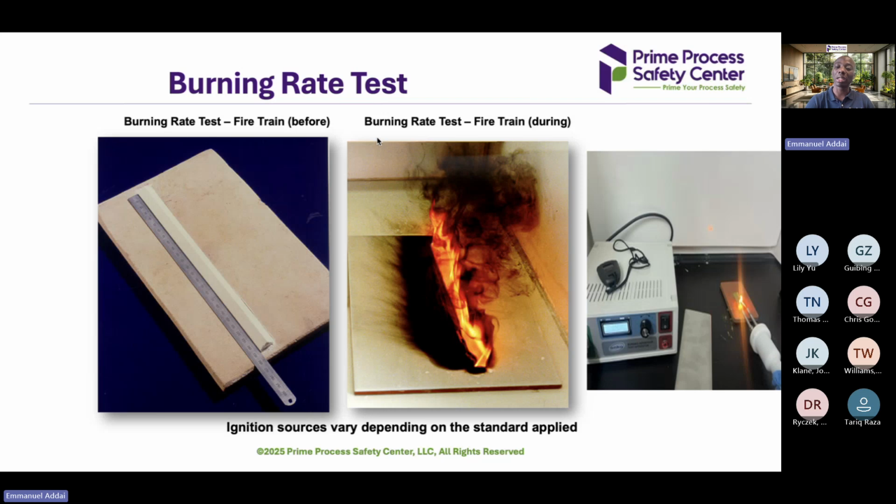What about if the material is not explosible? You test it and the pressure ratio is less than 2, and the maximum pressure is less than 1. Then the only thing that has to come to my mind here is that the material is not explosible. That means in the cloud form, I don't have that explosion risk. However, I might have a fire risk.